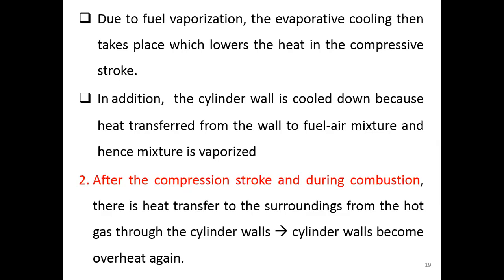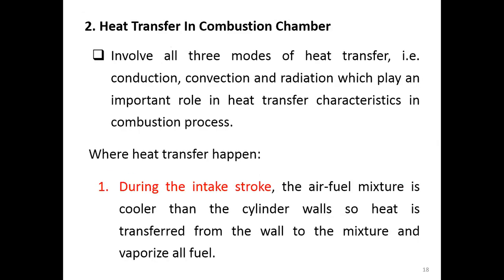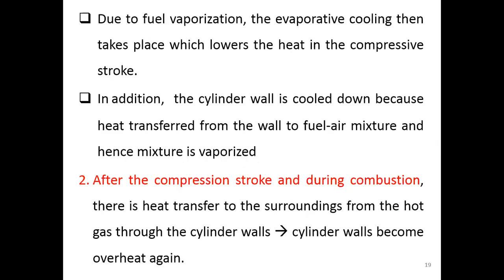So the heat transfer in the combustion chamber during the intake stroke is that we have heat from the wall to the mixture because the wall temperature is high. It just finished the exhaust stroke, and then comes the intake stroke, so the wall temperature is high. We have heat transfer to the fuel mixture, and due to that, we have the evaporative cooling. And this evaporative cooling makes the wall cool down.